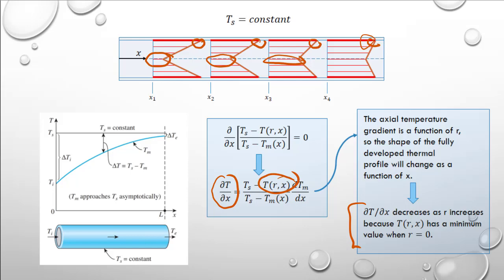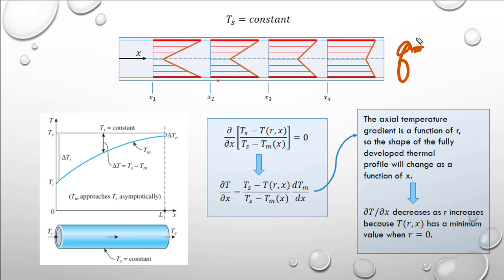And then the next step that we really have is to determine what is the h value, right? If we have q double prime equals h delta T, well, we still need to know what h is to fully define what's going on within our flow field. So that's going to lead us into the next video, where we'll discuss the energy balance. That'll then give us an ability to create correlations for the Nusselt number that will then reveal our value of the heat transfer coefficient.